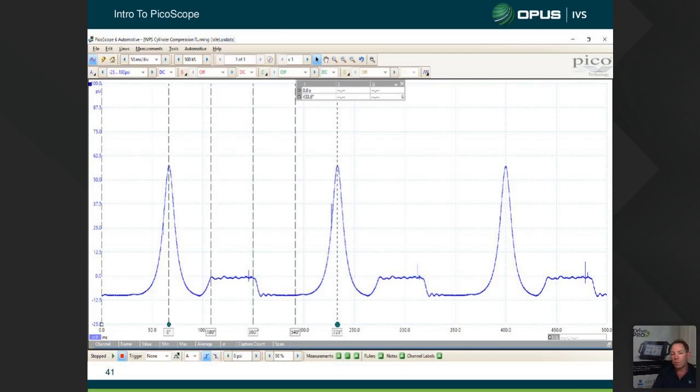And then as the piston drops down 180 degrees, I'm at bottom dead center number 1. Now I can see my values drop down there. So the engine has slightly gone into vacuum at that point. Now that would be our power stroke down there. So compression stroke, ignition, power stroke down. Then the piston starts to come back up again, you can see. So we've come out of that vacuum, we come back to atmospheric.